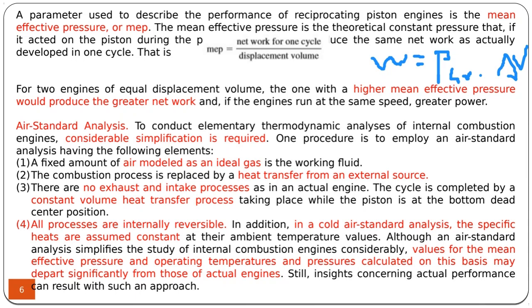meaning that we assume that there is no inlet of air or exhaust of gases, so that the same working fluid is used inside the cylinder, and heat transfer is provided not only from combustion but just from some external source, and heat transfer from the exhaust system is not obtained by the rejecting of the gases or expelling of the gases. It's just cooling the gases by some external sink.